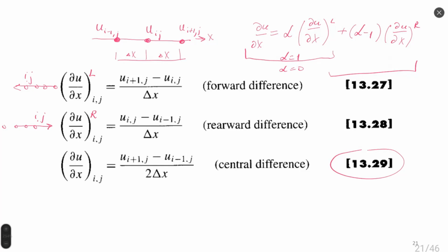or for flow solutions which are using some specific tool to mitigate or to calculate, let's say, some correction of flow. What I'm talking about, we will see very soon. So depending on flow direction, depending on the type of process we are calculating, depending on the parameter we are calculating, we use forward difference, rearward difference, or central difference.